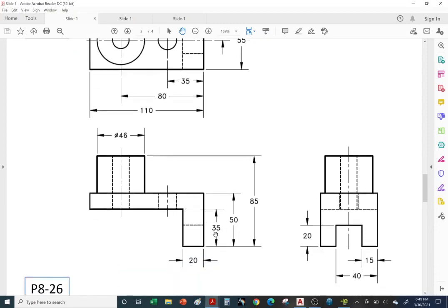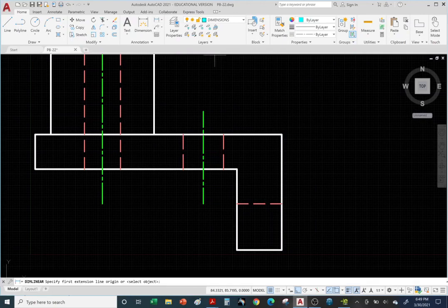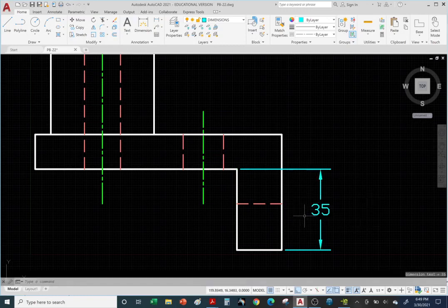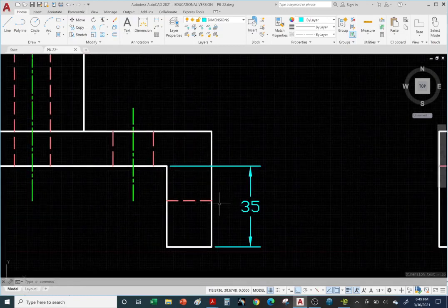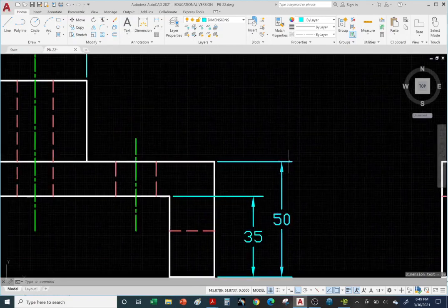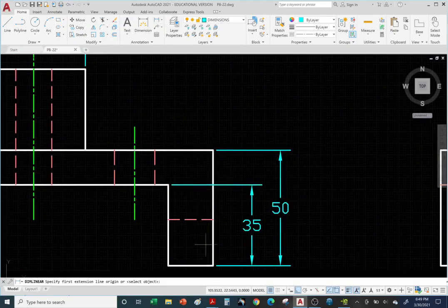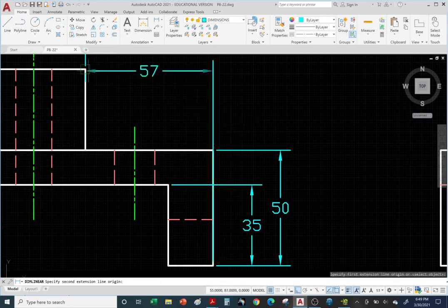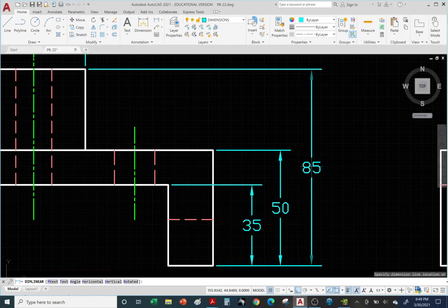All right, so let's go ahead and dimension bottom to top, and bottom to the very top. And then we'll also bring in the thickness of the wall. All right, so let's go to linear dimension. So let's go bottom to top. Okay, and always leave enough space for the first dimension. You put double the space. Go to the next dimension. And you work your way up from the small dimensions to the larger ones. And now here we can use 1 text height of space. And finally, the overall height. And space it out so it looks presentable.